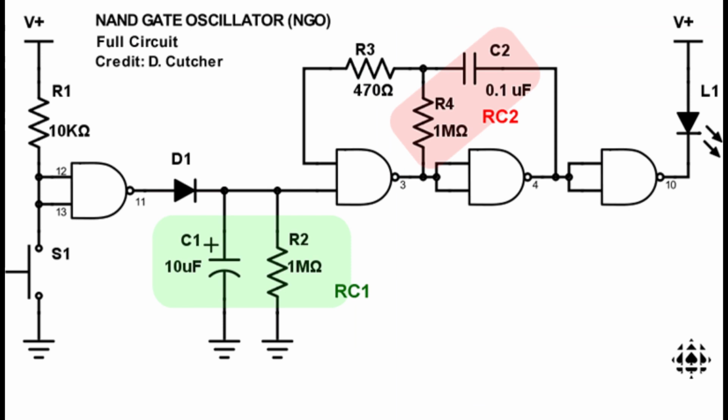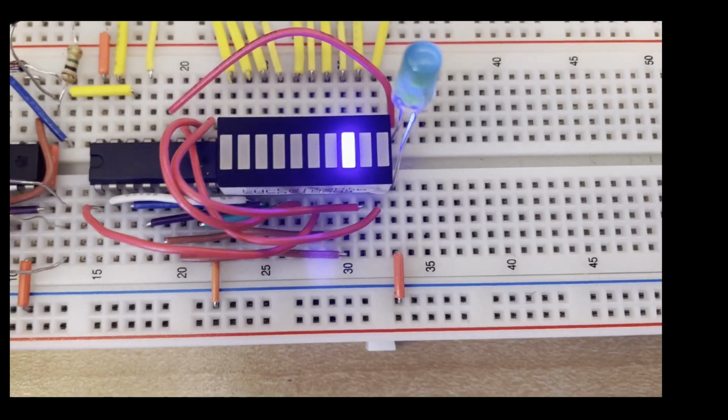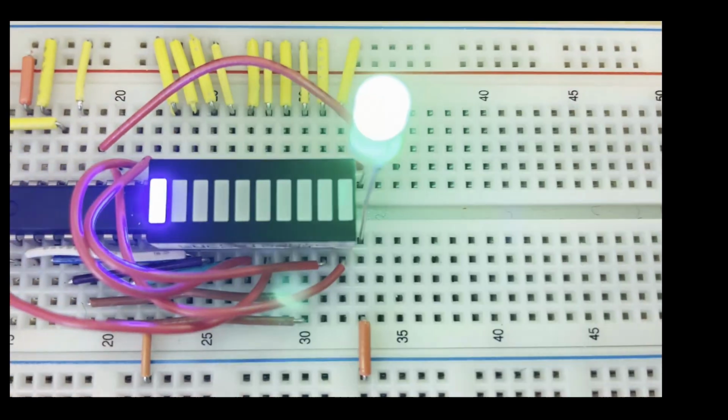The capacitor is able to create this oscillation because as it receives voltage and charges up, it also allows current to pass through it. This current gets inverted by the NAND gate, providing ground here. So, when the capacitor is fully charged, it expels all of its energy this way and can repeat the cycle forever. The next section of this circuit is the decade counter.